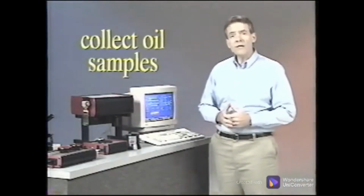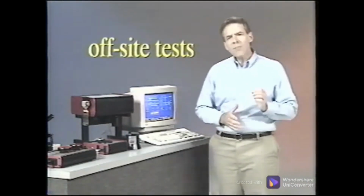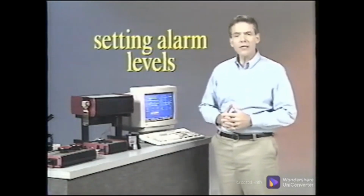We will consider how to develop a plan to use lubricant analysis as a means to detect lubrication problems and mechanical problems, as well as diagnose the source or cause of premature machinery wear. We'll look at oil and machinery conditions that can be diagnosed with on-site lab and with off-site labs. Steps and techniques are shown to collect oil samples and perform tests for certain conditions, and recommendations are made for off-site tests. Then, methods and rules of thumb are shown for setting alarm levels for the various machine parameters and machine types. First, let's look at oil analysis and see where it fits into your maintenance program.